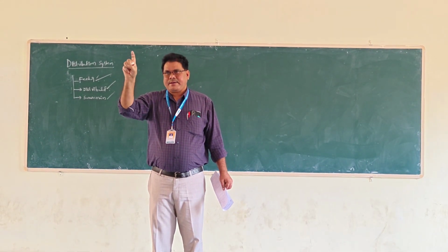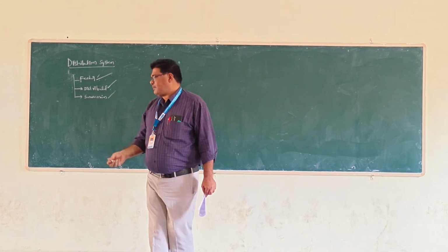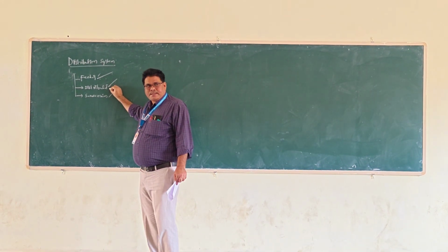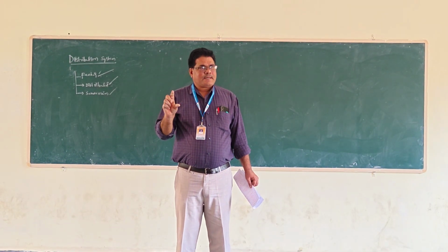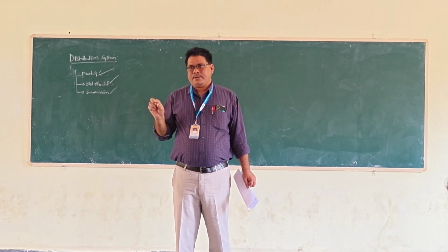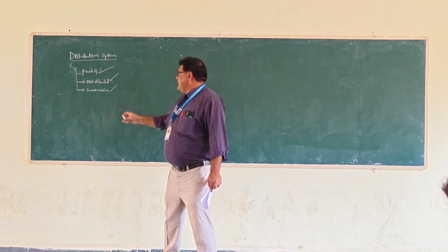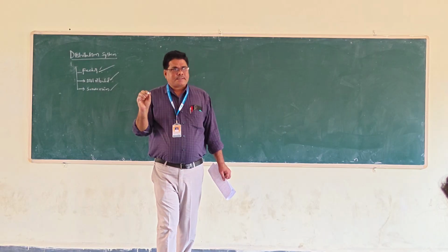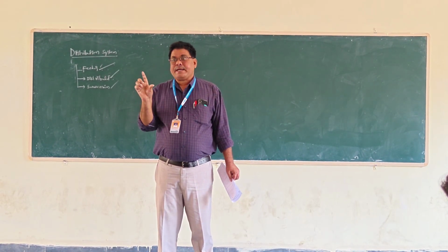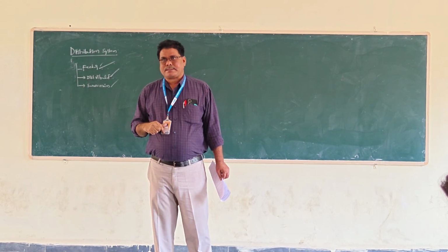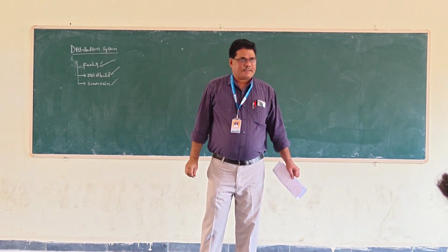Once the service wire is connected, there is a voltage drop, and the current does not remain the same. While designing a distributor, voltage drop is the main consideration. For a feeder, current carrying capacity is the main consideration.